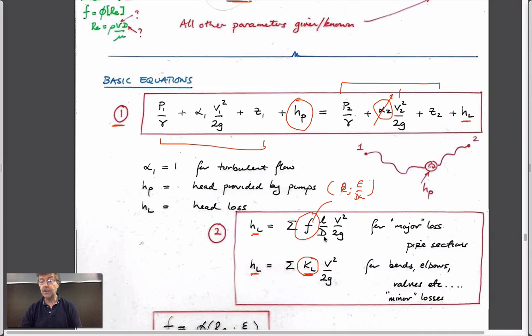When we're looking at major losses, they can be laminar or turbulent. We know exactly what the relationship looks like in terms of these 3 regimes, which are split up on some number, 2,000 to 4,000. In the fully developed turbulent regime, they're a function of relative roughness. And so these are no longer a function of Reynolds number once you get beyond this threshold number.